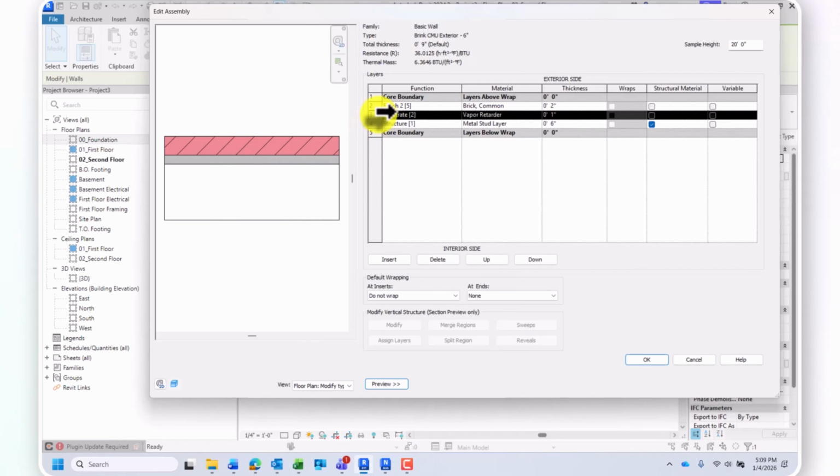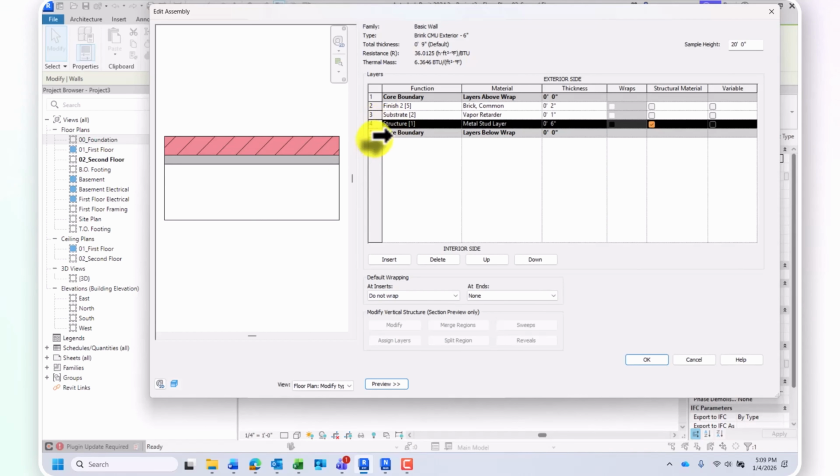As you can see right here, this is how we are aligned. See, I can hover over that. If I go up or down, watch this. See that? See the brick the same way. So you can see that these are the makeups of this actual thing. So now we got the stud layer internally. And if I want to do an interior face, right? Do one more just for interior face, right? Call it another drywall. So I'm going to insert.